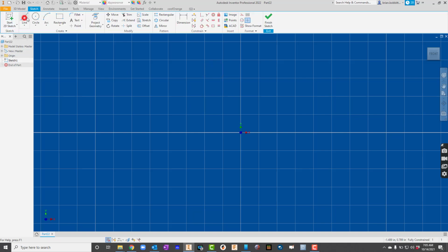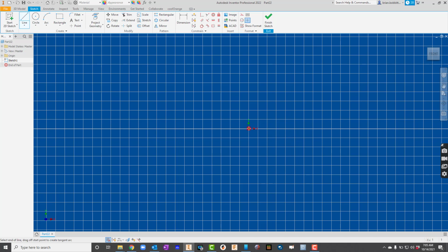Now I'm going to come in here and draw, let's draw like a Yeti cup. So I'll start at the origin, I'll come up here. Remember, on a revolution, we're just drawing half the shape. And it does something like this. All right, so it's like I stuck a pencil right down the middle of the Yeti cup for an axis, and then I drew the other half.